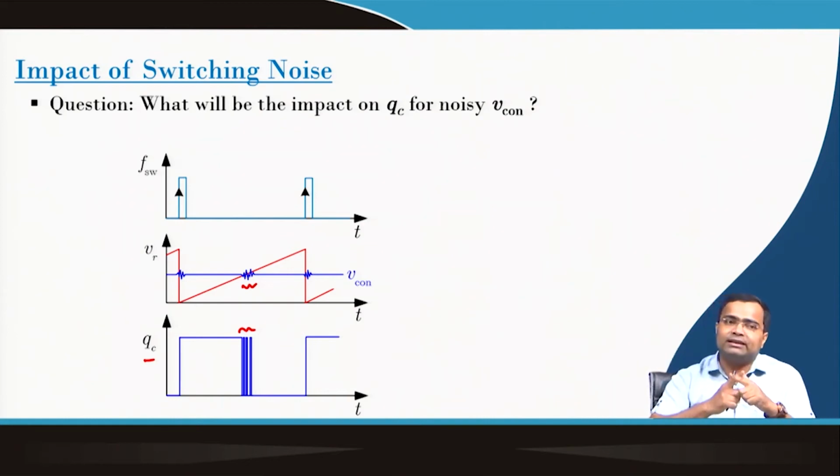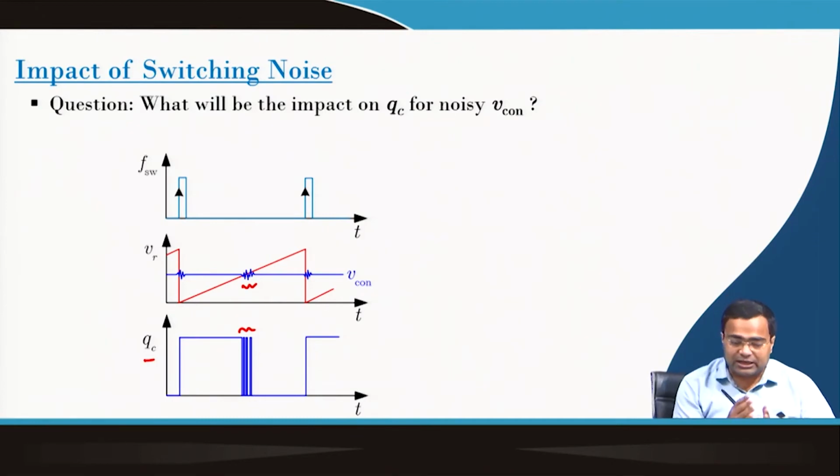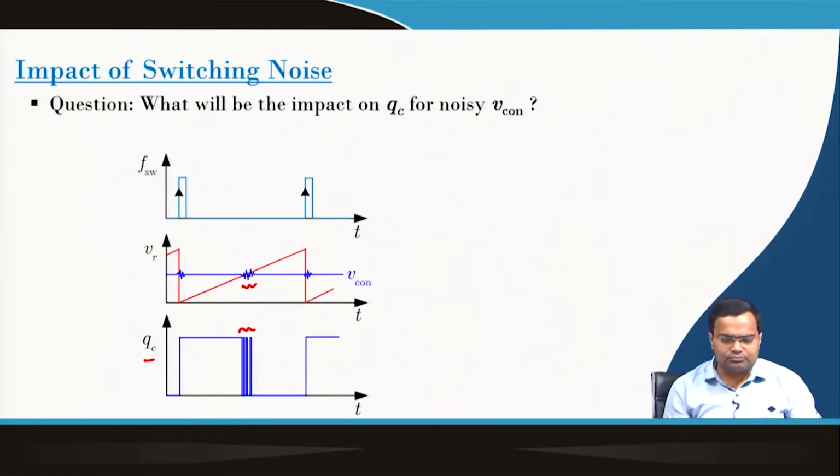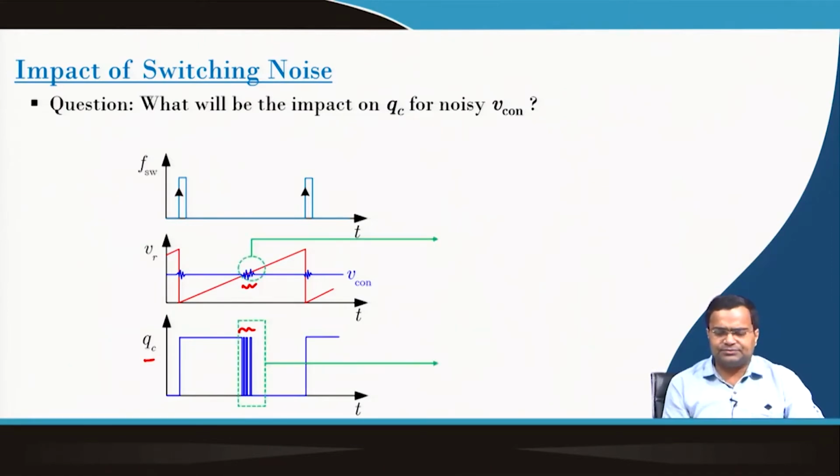Similarly, if you try to hit the limit in its rise and fall time, it can get heated, and if you continuously do that, it can even damage the MOSFET. So, such chattering is not recommended, and we should not allow it to pass to the gate signal. Then how to avoid chattering?